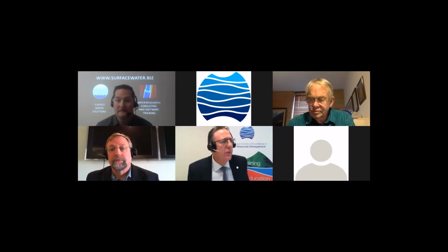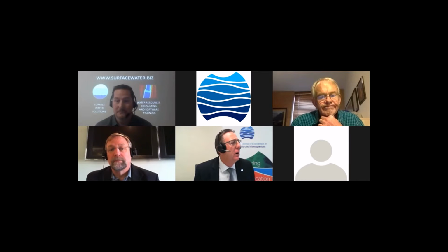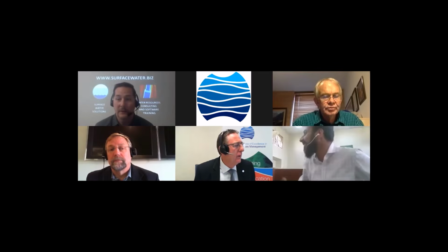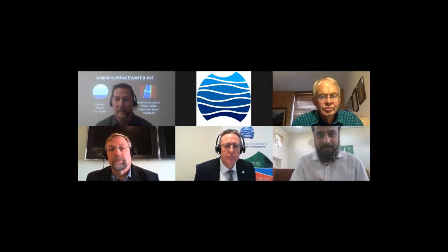Yep, that's great. There was one here from Dr. Sher Khan in New Zealand. Thanks for the great effort. Could you please advise a simple way to edit DEM? For example, cutting roads from the DEM. Yeah, and I think that goes back to that first question that we had, and that will be through the process called terrain lifting. If you Google HEC-RAS blog, then type in terrain lifting, it'll walk you through an exercise in how to do that. It's actually very straightforward. You put a roadway in. I can put a roadway in my model in about 5-10 minutes. It goes very quickly. That's great news.